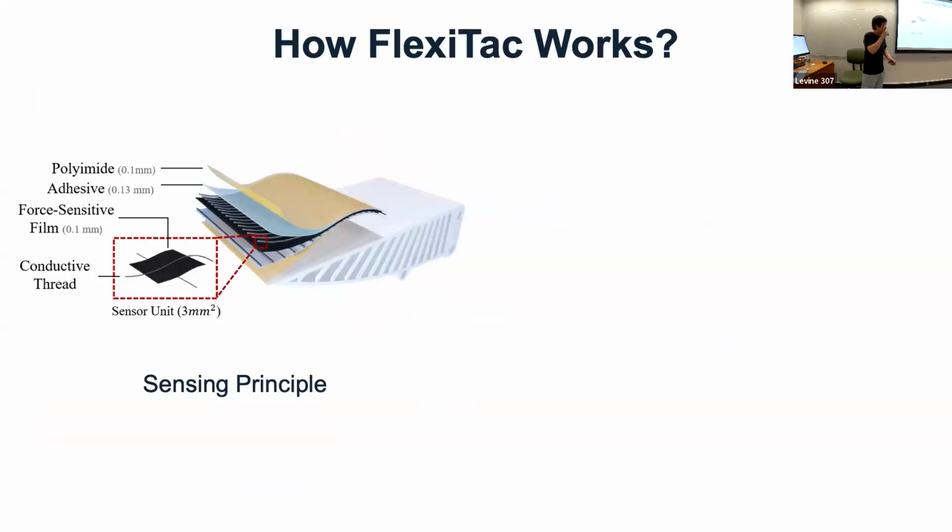Okay, now let's get started with our tactile hardware. This is the principle of our sensor, which I built during my first year of PhD. The name is FlexiTac; we recently gave it a name, and previously we didn't have one. The principle is very easy. The key material is this black mat, a piezo-resistive material. When you press it, the resistance of the material changes.